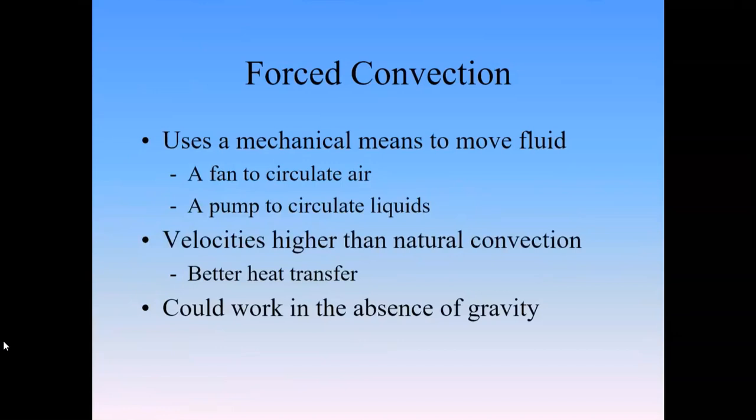So us pushing that fluid through allows more exchange of heat because there's much more movement of the fluid, and it does a much better job of either moving heat in or out of a system. The other thing is that forced convection could work in the absence of gravity. So if we were up in space, we'd have to rely on forced convection as opposed to natural convection.